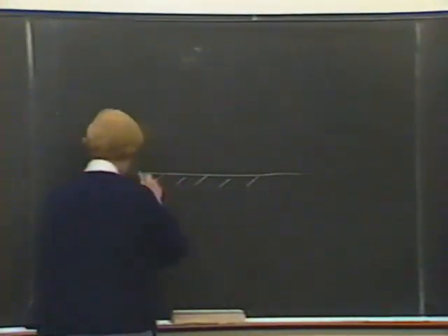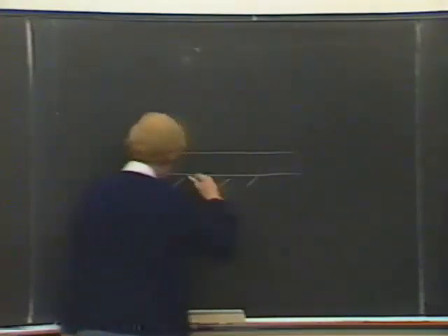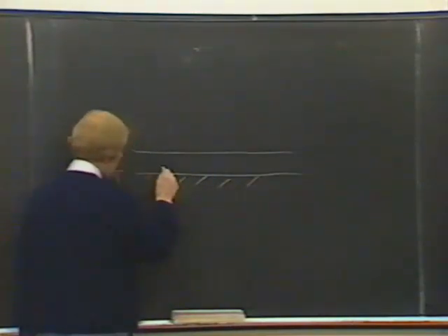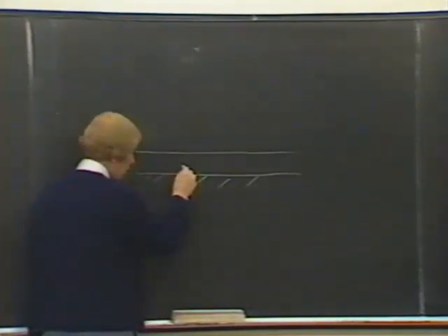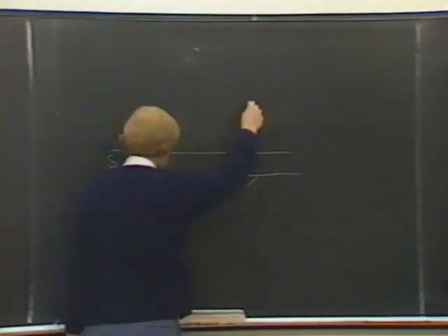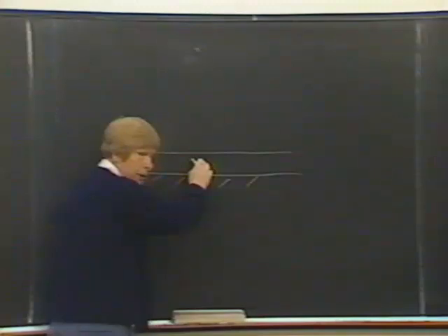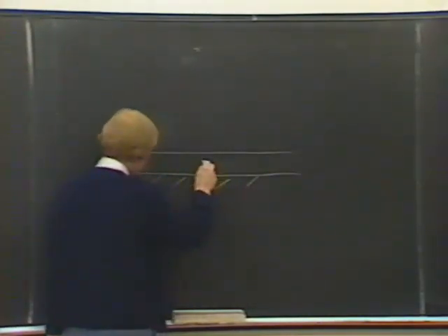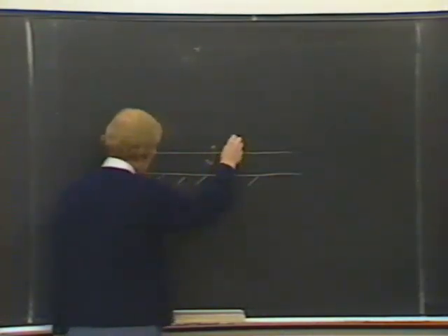And that particles, the velocity gradient in this layer is high. In fact, the velocity gradient in this region is the highest anywhere in the flow, in open channel flow. And that particles may be broken up into smaller particles and carried back up, and that larger particles are settling into this. The small ones are broken up, reform above, and settle back into this.